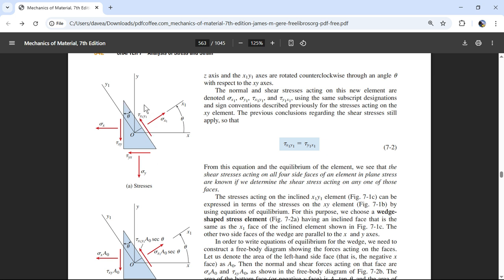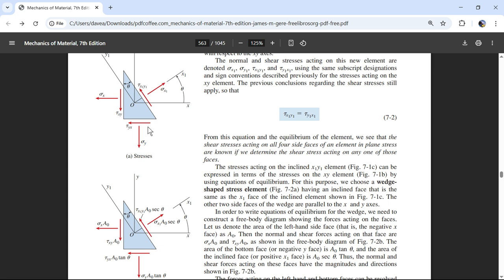That's probably the simplest way to visualize a shear stress: imagine duct tape on that surface and pull on that strip of duct tape. They're giving us the pressure that duct tape is exerting on that face. So we can figure out how much force is on that duct tape by taking the psi, which is pounds per square inch, pounds divided by inches squared.